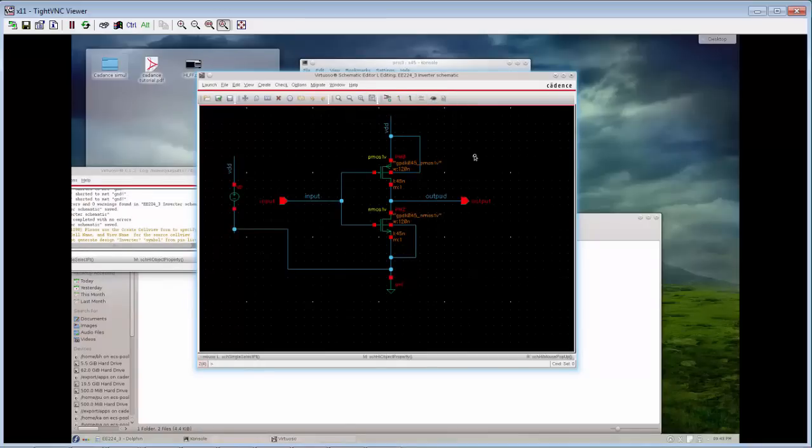If you would like to use this inverter circuit in other circuits, let's create 2 more pins like VDD and VSS, so that it will be easier to allocate the voltage sources in the other circuits. Because if you allocate this VDD and VSS, we need to again allocate for everything. So keeping other pins for the VDD and VSS would be a good idea. So let's do that.